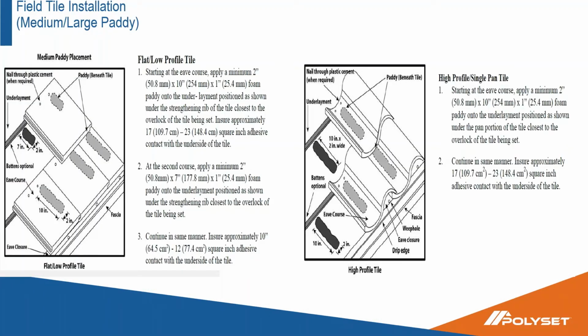The adhesive manufacturers, you can go into their installation instructions, and it tells you exactly where to place these patties, how to shoot them, and the contact area that's important for each different profile.